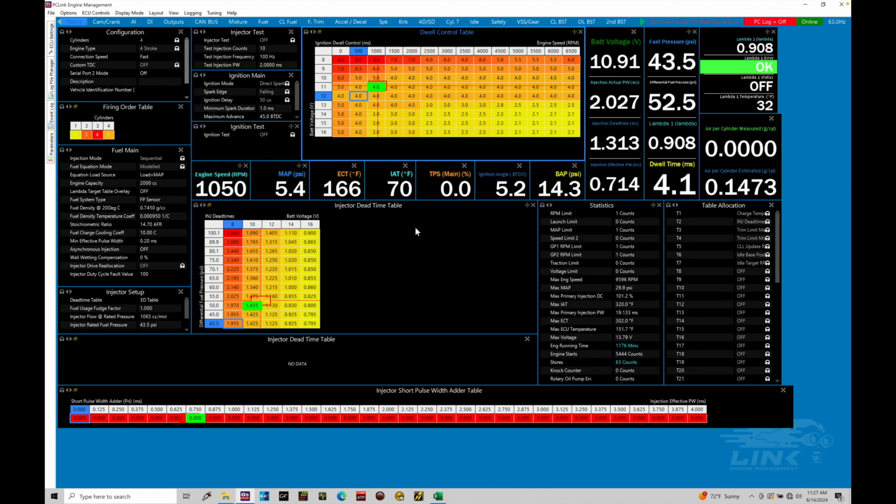Now, the reason why we want to bring in speed sensors, specifically wheel speed sensors, is for traction control purposes. We can detune the engine if we're overpowering the tire on the vehicle, and we need to measure the driven and undriven wheel to determine how much slip we have going on to allow the traction control to work. Now, we may not also want to use it for traction control purposes. If we're talking about launch control, we want to turn off our launch control at a given speed. We can use a speed sensor source to do that.